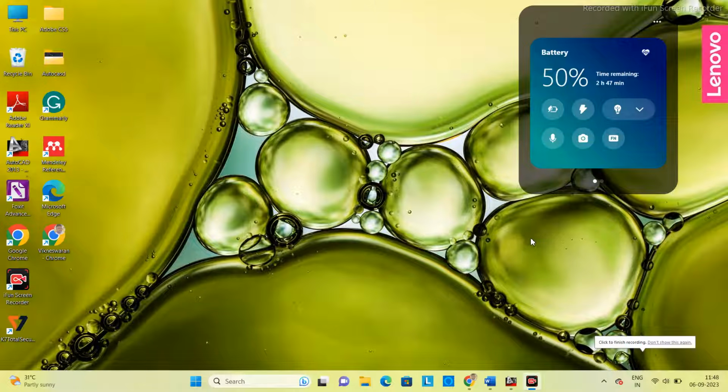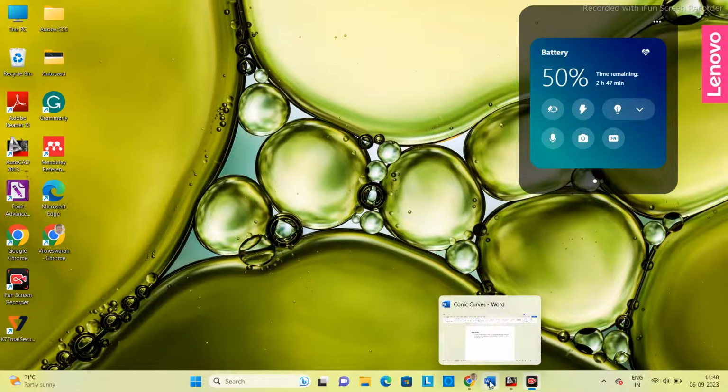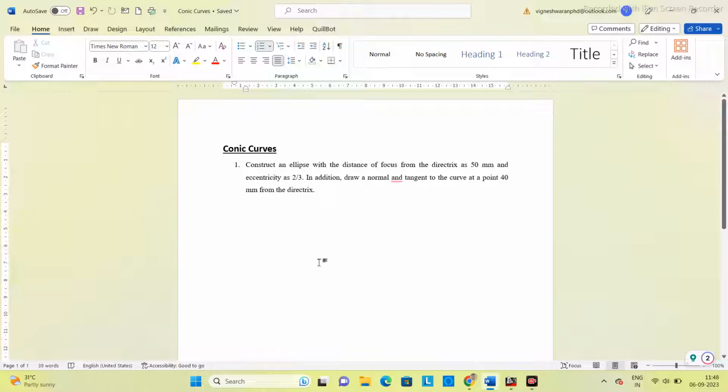Good morning, students. In this video, we'll see how to draw an ellipse using the AutoCAD software. First, let us see the question. Construct an ellipse with the distance of focus from the directrix as 50 mm and eccentricity as 2 by 3. In addition, draw a normal and tangent to the curve at a point 40 mm from the directrix.